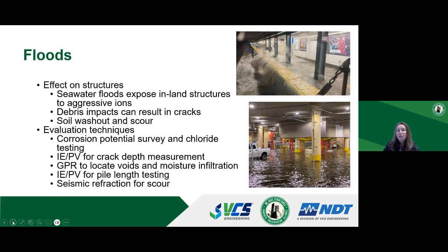With floods, there are several concerns. First, floodwaters carry with them a lot of moisture that can get into the concrete and cause reinforcement corrosion. If the flooding occurs in coastal areas, floodwaters also carry aggressive ions with them, such as chlorides, that can also diffuse from the surface into the concrete to the rebar depth and initiate corrosion.